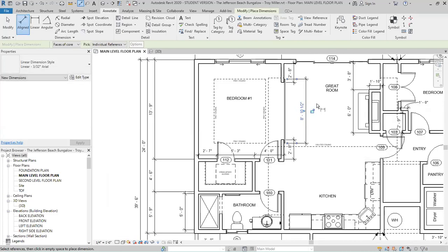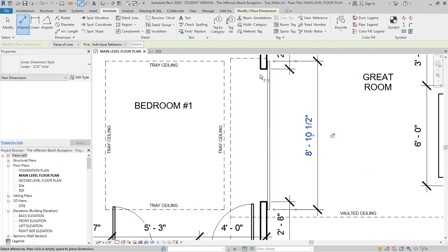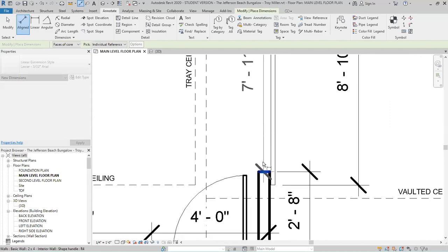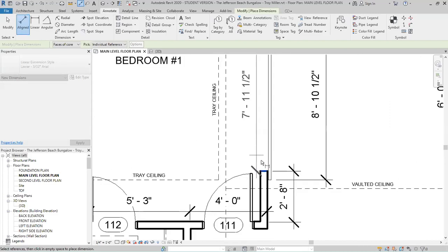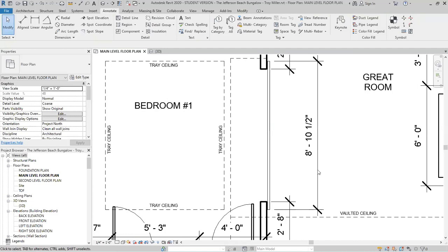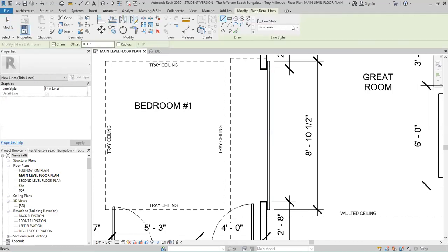I'm actually a little bit wider than that. I don't think this is going to work out. I think the door schedule is incorrect because if I measure that opening, I'm barely under 8 feet, and you need to have a little bit of overlap on each of those walls. So I'm actually going to make that a 9-foot wall.